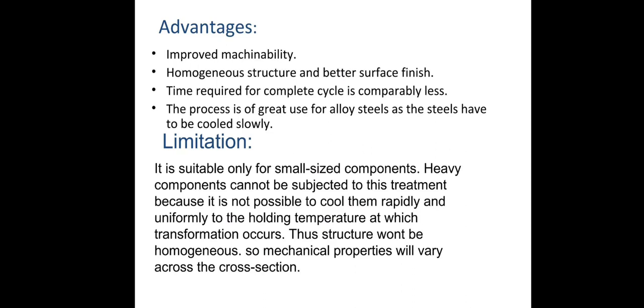Limitations: it is suitable only for smaller sized components. Heavy components cannot be subjected to this treatment because it is not possible to cool them rapidly and uniformly to the holding temperature at which transformation occurs. Thus, the structure won't be homogeneous, so mechanical properties will vary across the cross section.